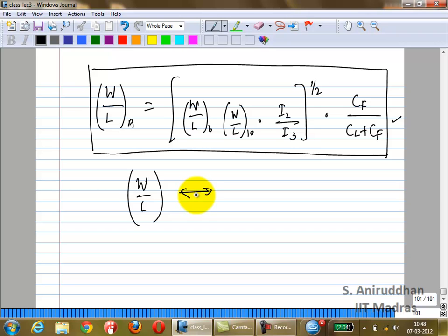What you'll have to try and be careful is, maybe you might have to choose the currents and sizes carefully such that you may want to get rational numbers, for example, right? So that you can lay them out very easily. Definitely you don't want irrational numbers. If you're trying to mirror the current, you definitely don't want to have one size as 10, other size as 11.3417 or something like that, right? You definitely want to have laid out in units which can mirror your current very well. Okay? Your W over L, ratio of resistors, ratio of capacitors.